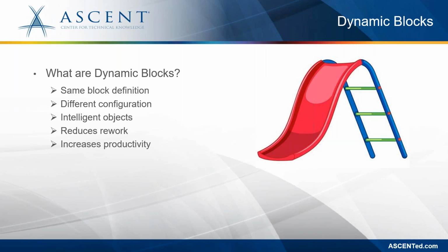What we realized was that each equipment, for example, there was a slide, and the same slide came in 4 different sizes. So instead of making 4 separate blocks of 4 different sizes of slides, we started by creating a single block of the slide. And then we would incorporate all the 4 sizes within that same block. That's what a dynamic block is, and that's where the difference between a standard block and a dynamic block lies.